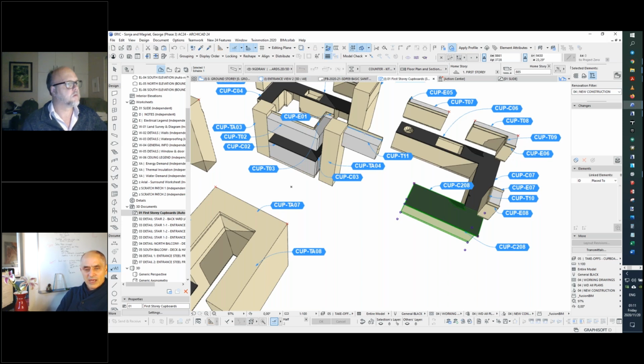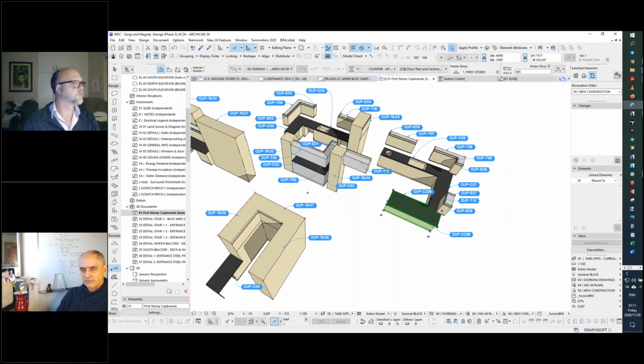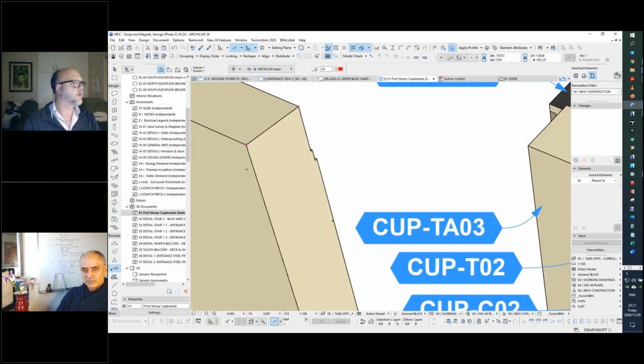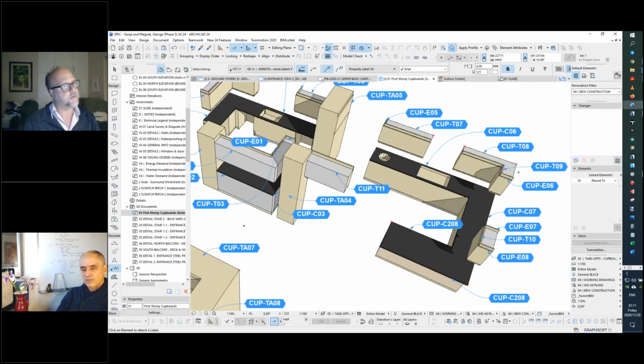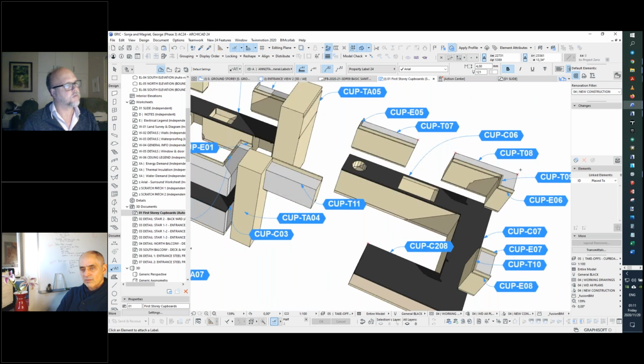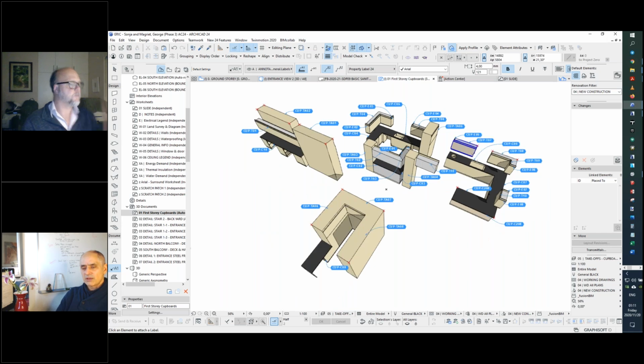Now, by the way, you have all of these little X's at the corners. Is that something that you've manually placed, or did ArchiCAD do that for some reason? These are hotspots that I placed for easy dimensioning. Okay, so you've placed these hotspots in 3D space by snapping to those elements. You're just using the hotspot tool? Just using the hotspot tool and placing the hotspot on the 3D document. Right, okay. And so that allows people to see sort of where you're dimensioning between more easily.